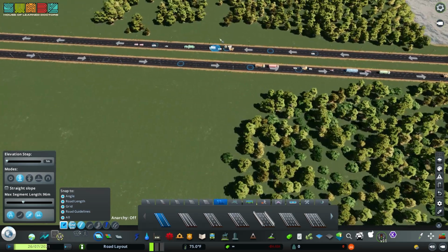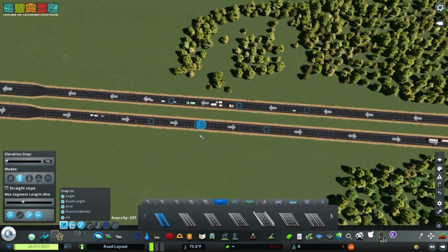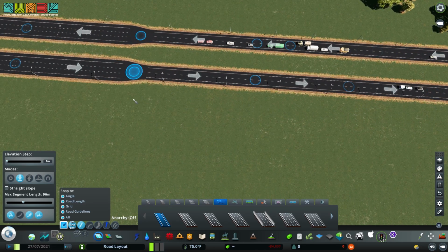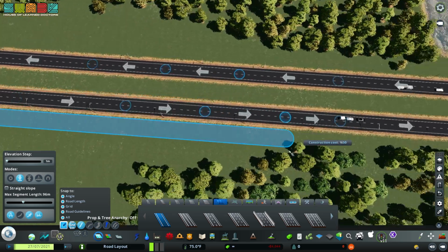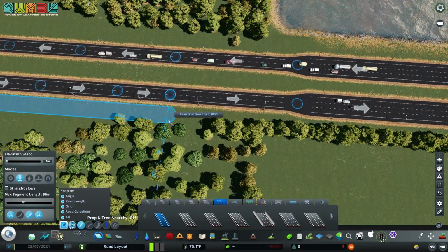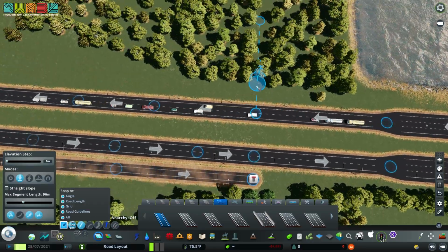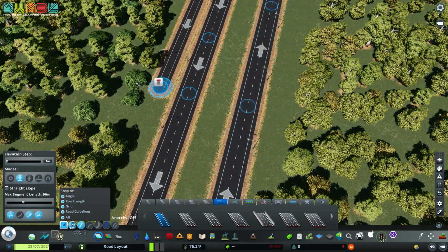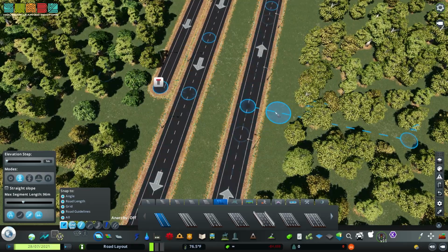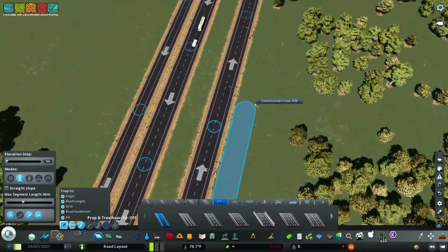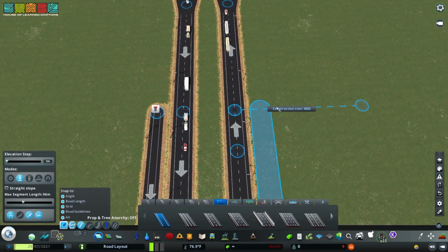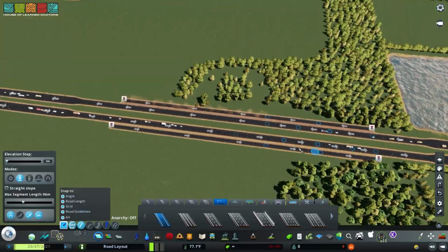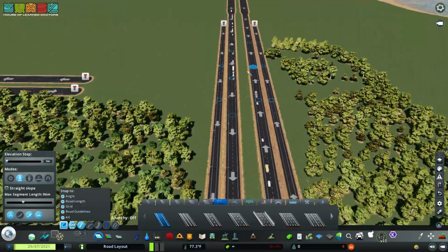And to that point, I want to see how wide this is going to be once all of our roads are determined. So for the whole area that we've just reduced down to 2 lanes, I want to make our ramps. I want to give us a width just as a guide. 2 units, 16 meters. Yep, 2 units, 16 meters is looking good. We can go perpendicular off of our road guideline. And there we have it. So that's the width that we're going to be working with.